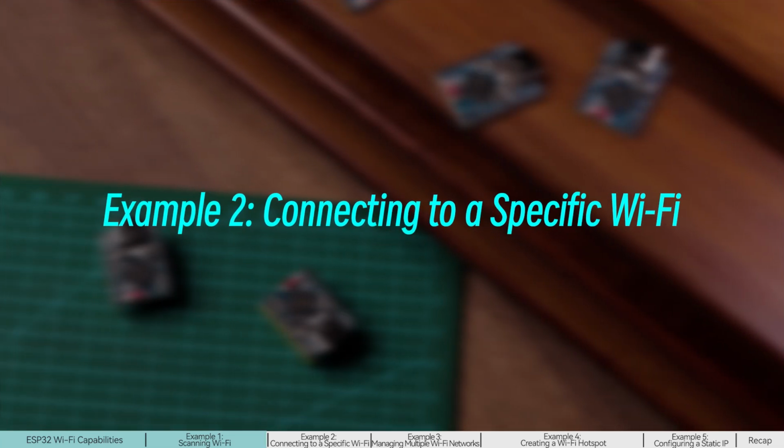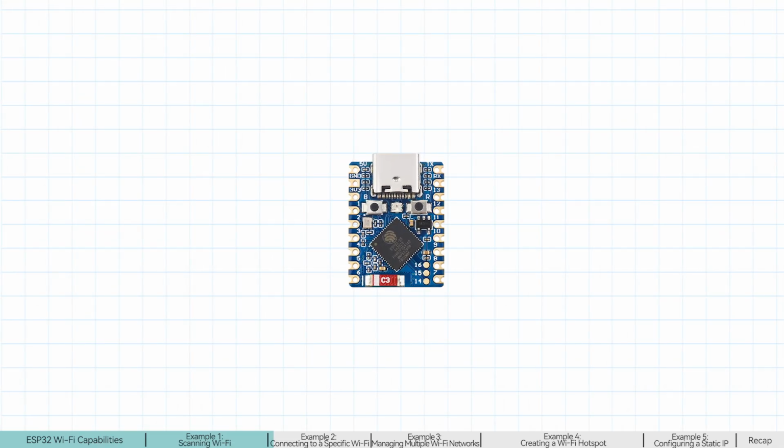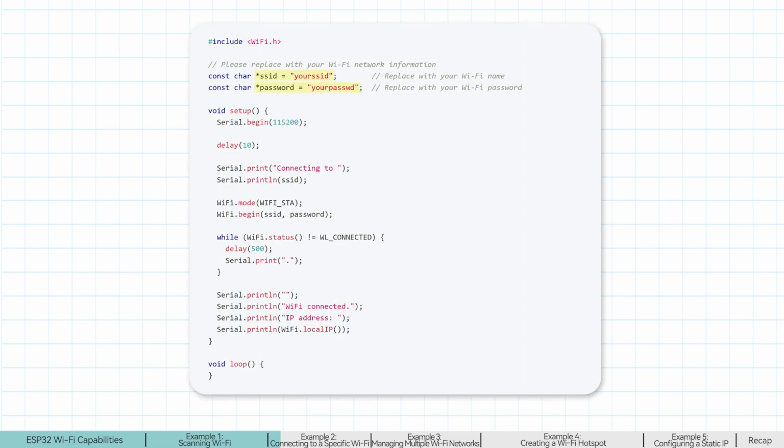After scanning for networks, the next step is obviously to connect to one. This example demonstrates how to make the ESP32 connect to a specific Wi-Fi network. First, define the network SSID and password. Set the two constants ssid and password in the code, replacing them with your Wi-Fi name and password.